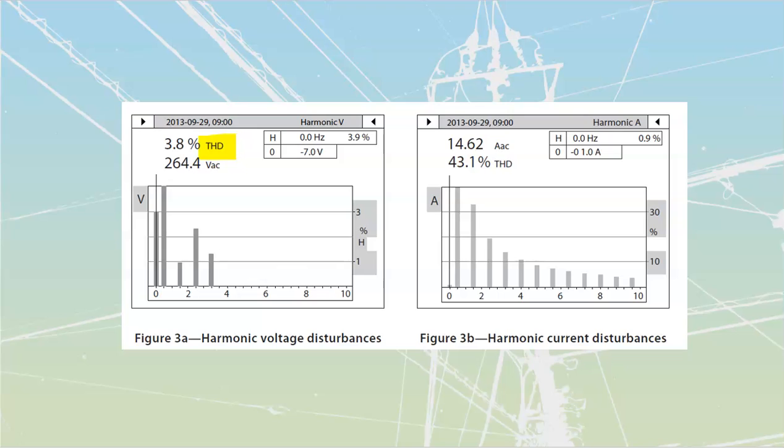If you're having problems with motors overheating, it could be that we have zero sequence. That would be a neutral thing, but that would be uncommon for us to necessarily have motor problems. It's more common that for the motors, we're looking at either positive rotation, or negative rotation that's going to be counteracted. So when you take something like this, this is going to allow you to see which of your individual harmonics are going to be spiking at any given time,